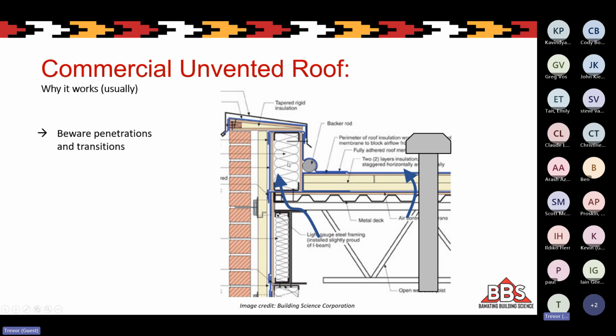And obviously the parapet itself has cold on almost all sides of it, and moisture accumulation inside the parapet wall can be a real issue. So maintaining the air barrier under the parapet wall is really important in a design like this.